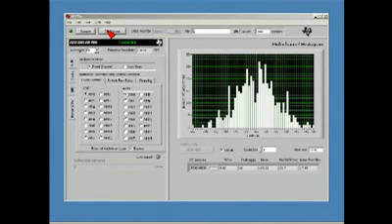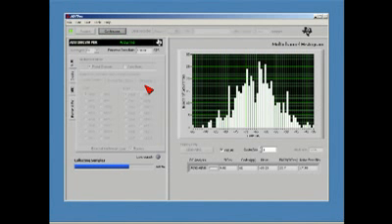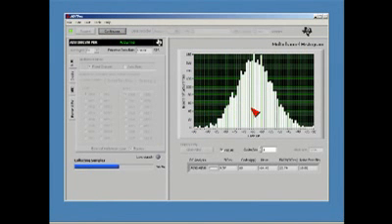If you apply a DC signal to the ADC and record a large number of samples, the result will be a distribution of codes. We will take our measurement by applying 0 volts and shorting the differential inputs of the converter together. That's why you are going to see that the center code of the histogram is 0. So let's look at the results. You can find the standard deviation, or ENOB, underneath the histogram.